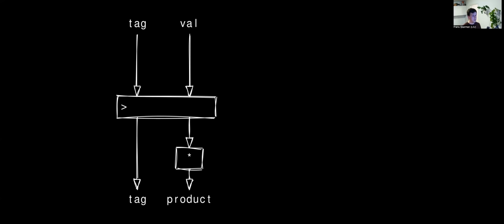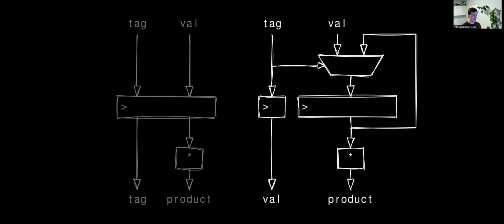A way to write this that saves dynamic power is instead writing this, where we use the tag to choose between keeping the old value or getting in the new value. With this, we don't switch this unnecessarily. We won't switch it for invalid data. We'll save power. Looking at it like this, we'll probably sacrifice area because a multiplexer isn't that cheap.